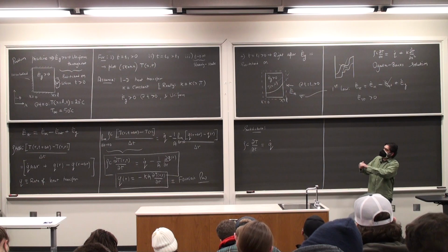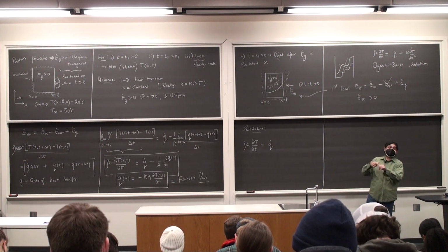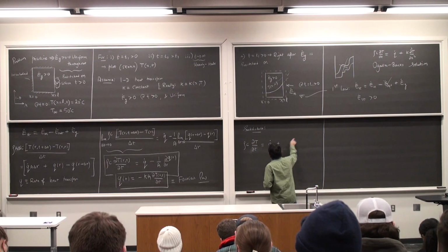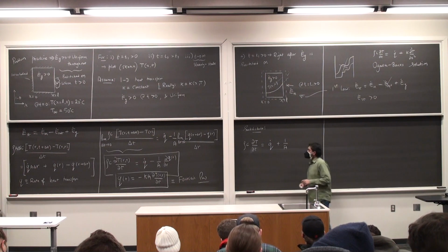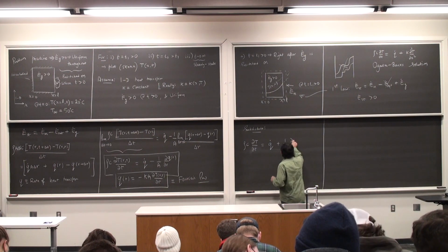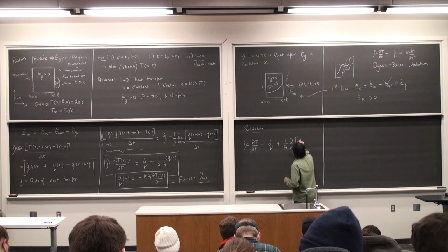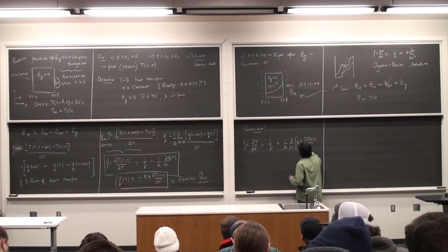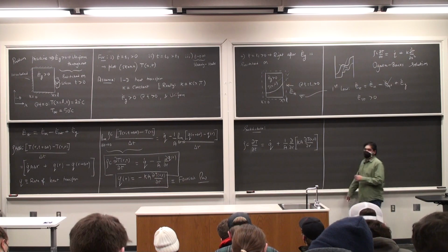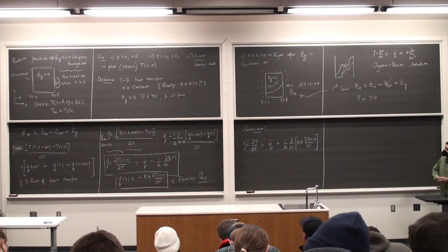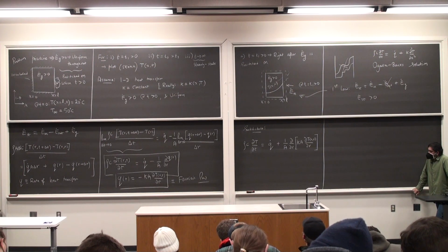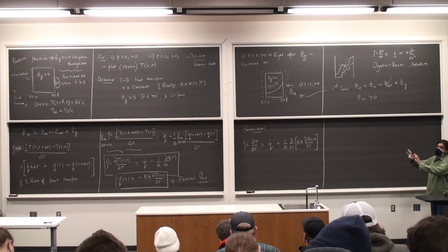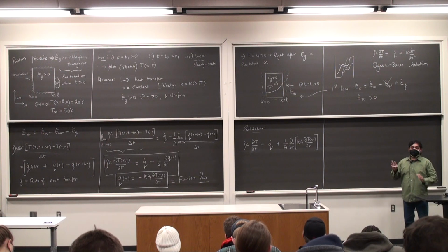I have a negative sign, 1 by A times dQ by dr, but Q of R itself has a negative sign because it's proportional to the negative temperature gradient, so it becomes positive 1 by A d by dr of K times A times dT by dr. And now this is the most general one-dimensional heat diffusion equation.